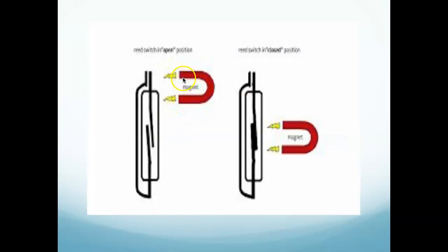So that part that's mounted on the door, the one that didn't have any wiring, is just a magnet, and it sits on the door. This one sits on the frame, and inside it has two metal reeds. And those reeds are either apart or they're together. When the magnet on the door, the one with no wiring to it, right, is close enough, it's pulling those two reeds together and it's connected. When you open the door, the magnet's not pulling on this one anymore and they separate. They're slightly bent and they separate. And when they separate, that's what sends the alarm in. It's that simple.